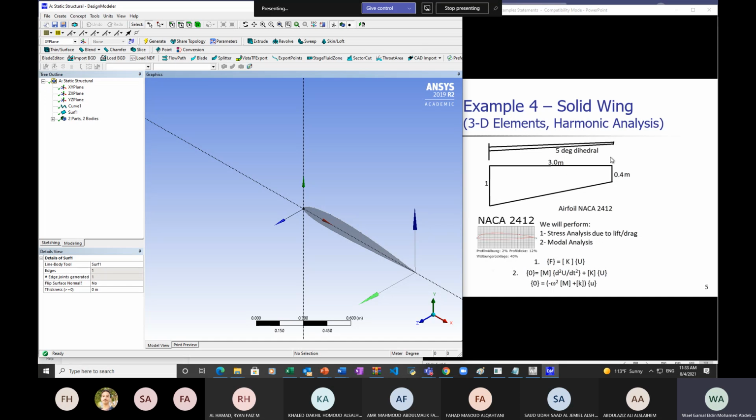I will create another plane to draw on at the tip here, 3 meters away, and I will draw the other airfoil. So in order to create the plane, you see this symbol here, it's new plane, creating a new plane. So I'd like to create a new plane so that I can start drawing there. Where do you want the new plane?